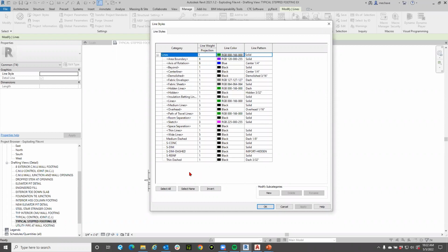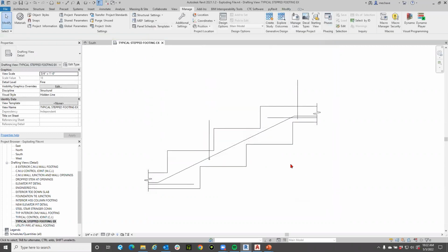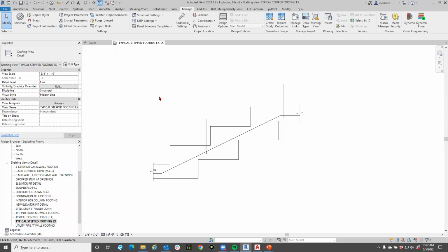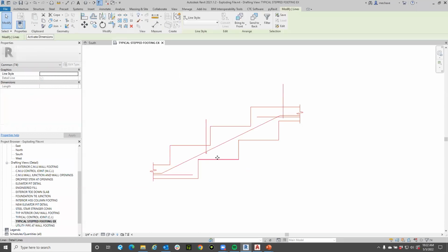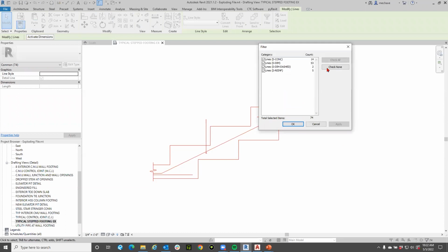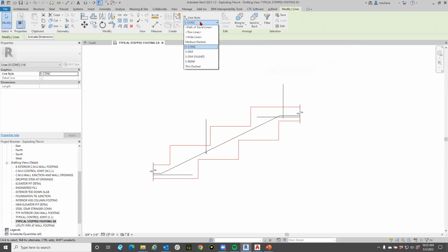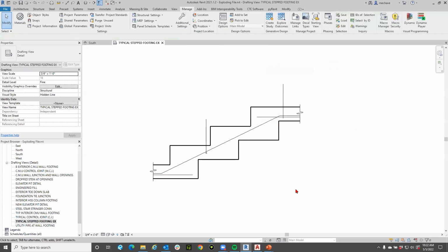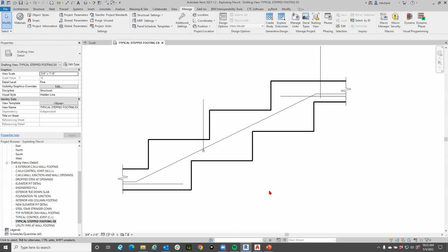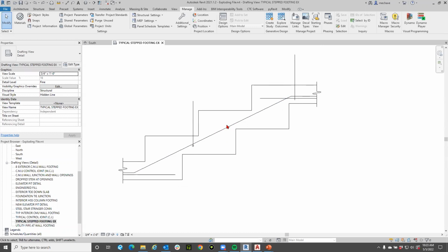So what we're going to do here is, I'm not going to do it from this view, but the other way would be, right, okay, they did transition over, okay, so now we're done, now we can go and dimension things. Or I would have to go through and highlight each view, grab whatever one was supposed to be on something like, hey, I know concrete was supposed to be on a line style of wide lines, right? So that I can see my line styles. Maybe that's my process. That was the old way, right? I don't have to go through and do that with the tool that I'm going to show you next.